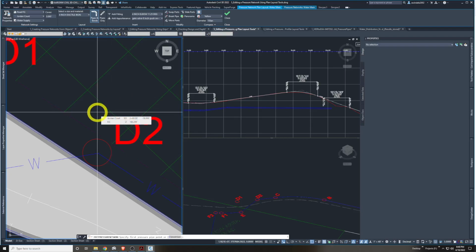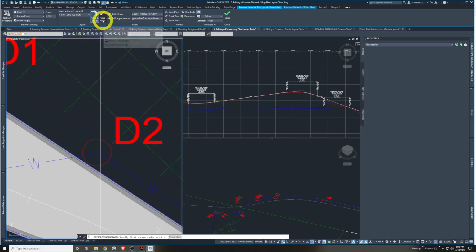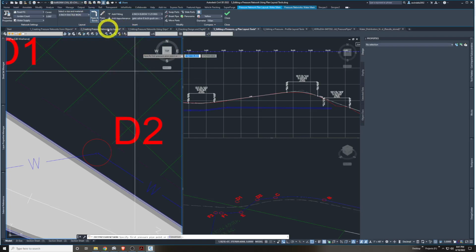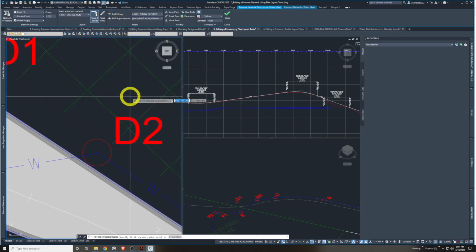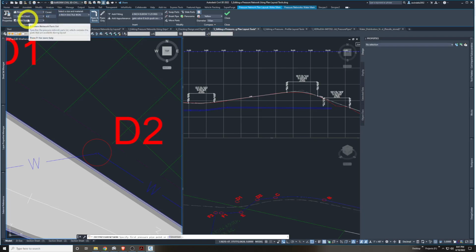Now I have this going here, and this is what I was trying to find in one of the first exercises. I have pipes and bends and pipes only. This is what I was really looking for. We can add fittings and appurtenances as we go. We're going to check a few things in the ribbon first. We're going to verify that road FG is the selected surface, which it is. We're going to verify the cover is 4.5 by default, which it is now.